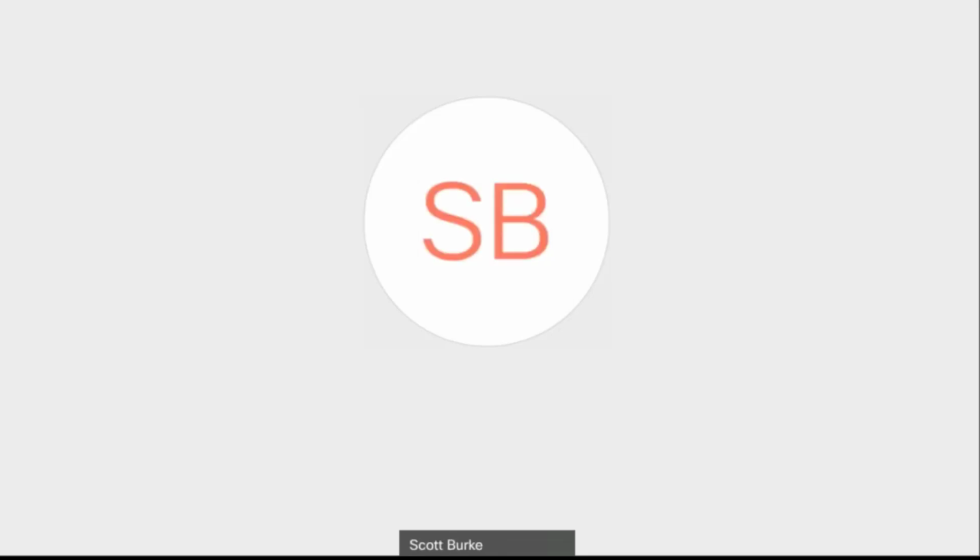All right, thanks. So another question, what's the best way to have two people work on a Revit model at the same time other than using worksets, to avoid having to ask for permission from the other person using the files? Really, there is no best. The best way to have two people work on a Revit model is worksharing, and that is really what it was created for, to be able to work together on a model. You check out the items you work on, and when you save to central, you relinquish access to them.